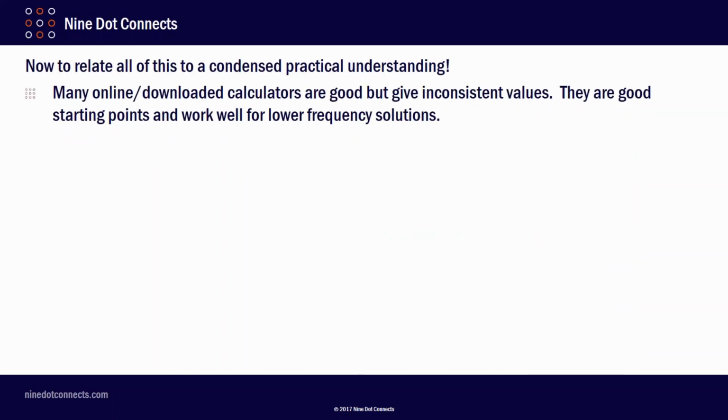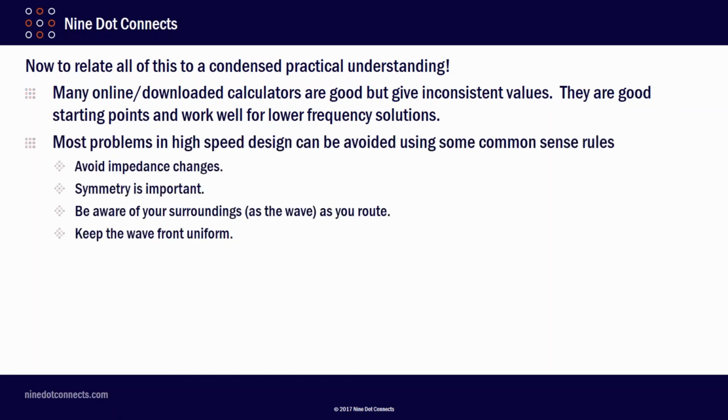Now, to relate all this to a condensed practical understanding, many online downloaded calculators are good, but they give inconsistent values. They're good starting points and work really well for lower frequency solutions. But as you move up in higher frequencies, you really need to either get a Stackup planner that includes field solvers or use a 3D field solver yourself.